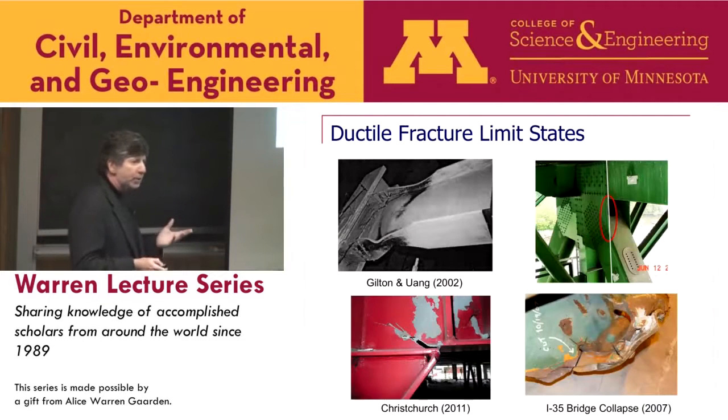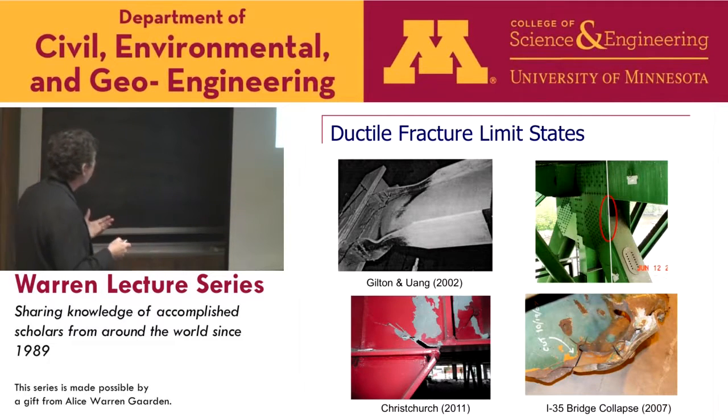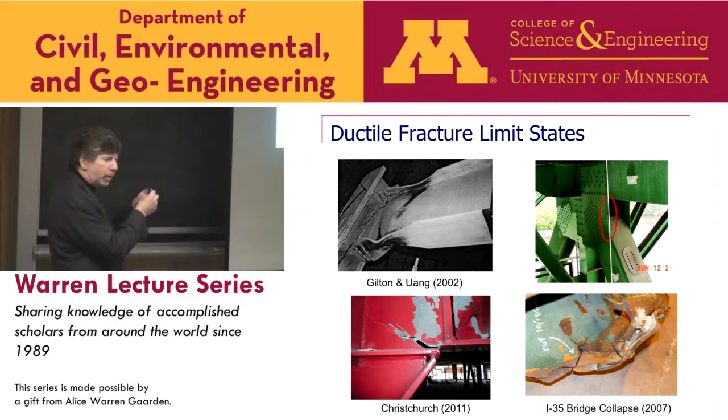And the ductile fracture models are ones that could be more generally applied to look at steel structures, when we look at local buckling and tearing, things like that, to be able to simulate tearing and ductile fracture. And of course, the tragedy a few years ago on the I-35 bridge here, tearing of gusset plates, it's a sudden fracture, but metallurgically, it's more typically a ductile fracture. An example I'll show later from the damage to a building in the Christchurch earthquake.